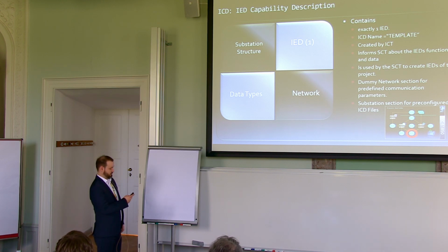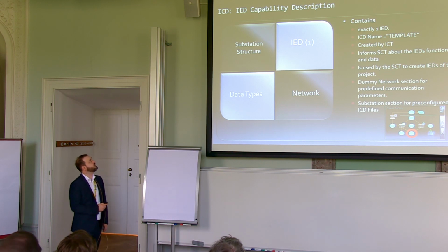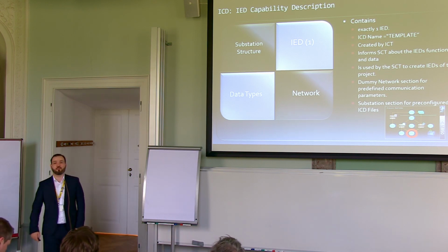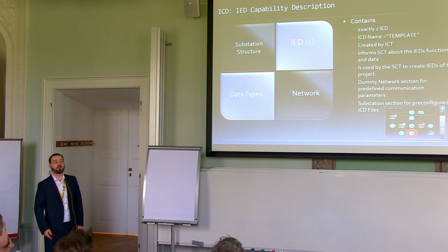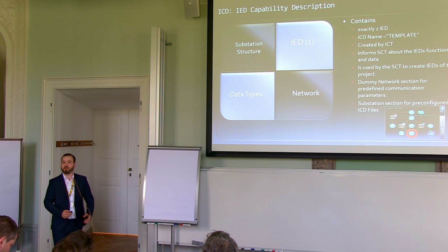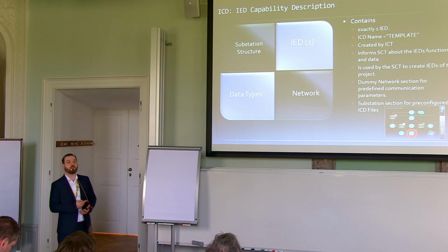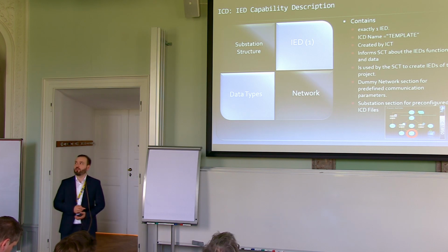So there is a possibility to add some part of substation structure, for example, to illustrate the use of this ICD in a given bay. It's neither mandatory, nor will most tools make use of this. So they will import mostly the IED section and, of course, as always, all the data types that are relevant.